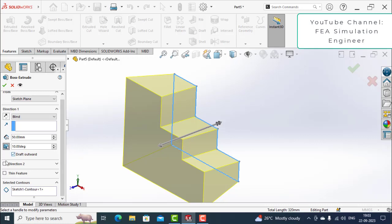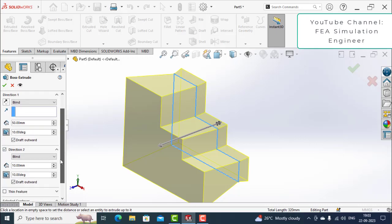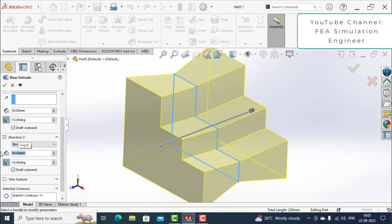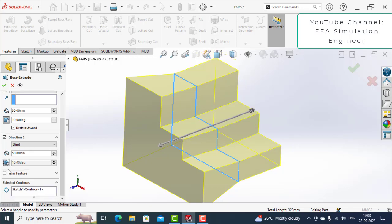You can select direction 2 also, so that wherever you have drawn the sketch in the front plane, from that plane the opposite side also the material will be added. See, I am just changing the total depth here, again 50 units to the other direction. Similarly, the draft feature is automatically added for direction 2 also. If you want, you can keep it, otherwise simply switch it off.